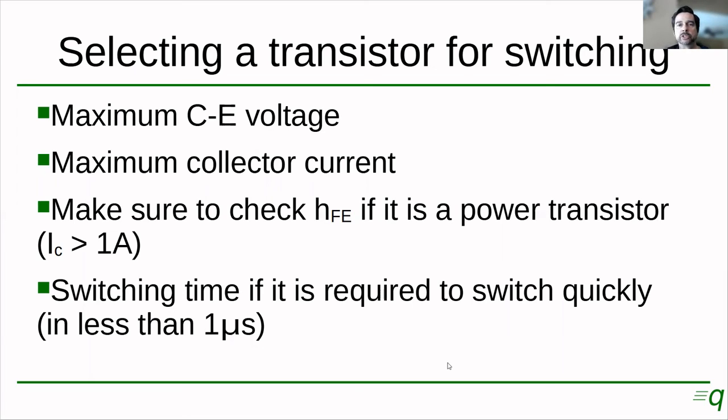And the last one, which may or may not need to be reviewed, is the switching speed, right? If you need your load to switch quickly, say in less than 1 microsecond or so, you would have to make sure the transistor is fast enough for this.